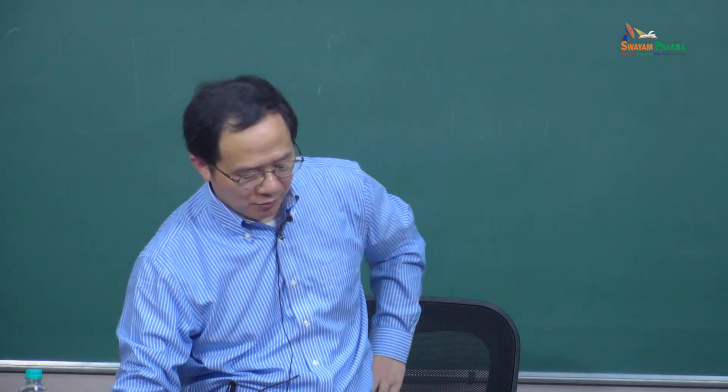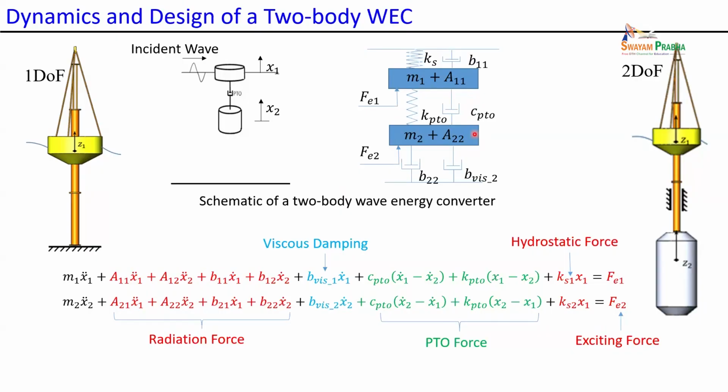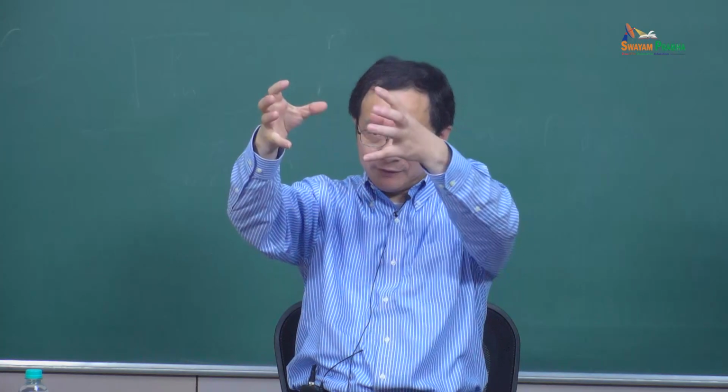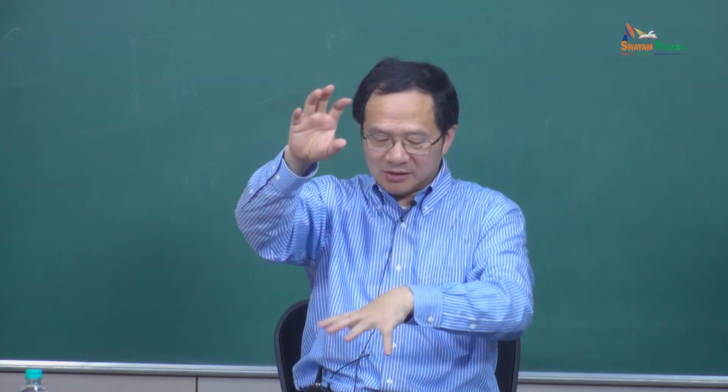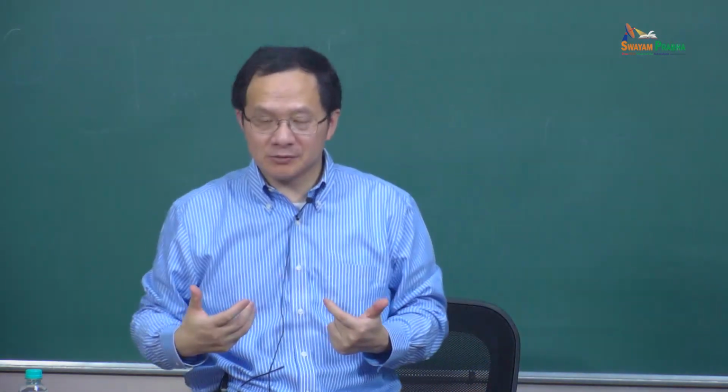This is I11, this is B11, and this mass moving creates such radiation damping. Also, the motion of the second body creates a radiation damping force here. This is B12, this coupling. Similarly, if the distance is large enough compared with this mass, then this coupling term disappears.